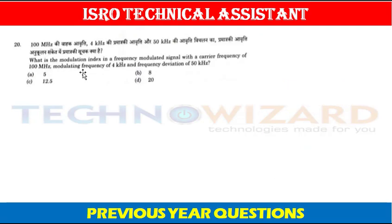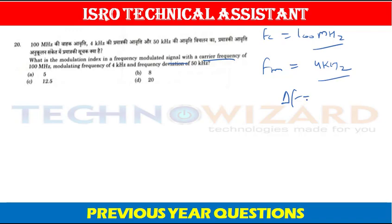Last question, question number 20. What is the modulation index in a frequency modulated signal with carrier frequency is given as 100 MHz. Modulation frequency, that is FM, is given as 4 kHz. And the frequency deviation, that is del F, is given as 50 kHz. Okay, we have to find the modulation index.